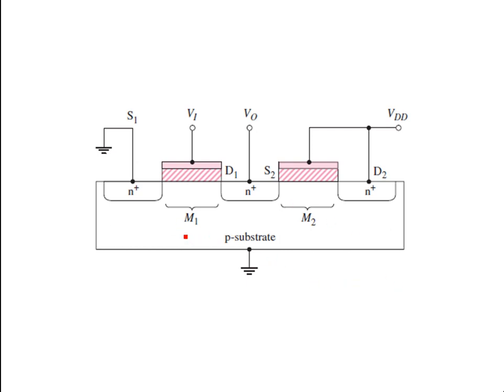You see over here, for example, you have two NMOS devices, M1 and M2. Because it's an NMOS device, the channel is established by applying a gate voltage at least greater than the threshold voltage of both devices, VTN1. Then we have another gate voltage, let's call it VG2, greater than VTN, which is already shorted with the VDD, so it has to be greater than the threshold voltage anyway. So we have two devices, M2 and M1. This voltage is required to establish a channel in both devices.